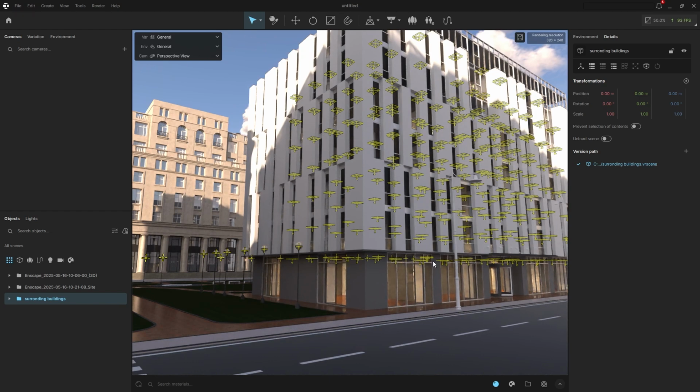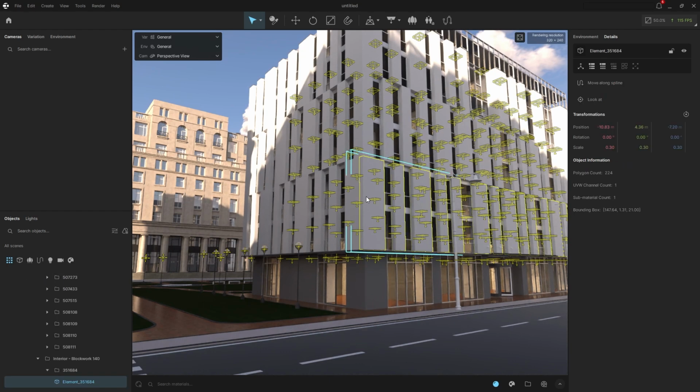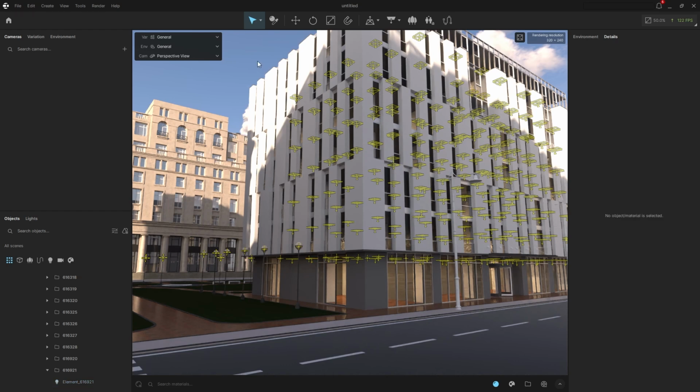And again, this is probably the biggest thing. All the geometry comes across, all the materials come across, all the lights come across as well. Everything is selectable. And notice the Revit file that we have, all the categories came across from Revit. So walls, windows, lighting fixtures, doors, things like that. Now we can do object level manipulation. We can also click on individual lights, adjust that intensity as well. If our scene did not have lights, we can also add lights in from inside of Envision as well. But again, object level manipulation, that's where we can manipulate any piece of geometry inside of the scene.